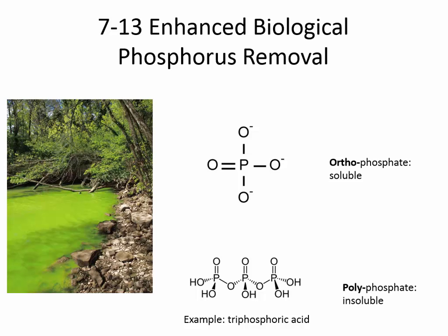It doesn't cause the bubbles, but what it does is tie up calcium, iron, manganese. Phosphorus temporarily will bind to hard water polyvalent cations, the things that cause hardness in water. The phosphorus can temporarily keep them busy so that the detergent is able to foam and be more effective. And so phosphorus is a water softening agent.